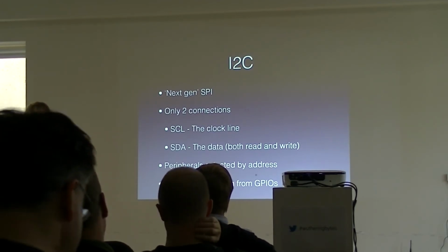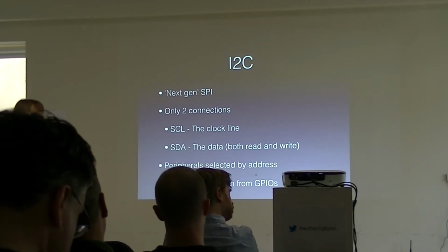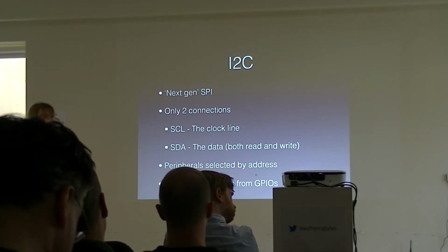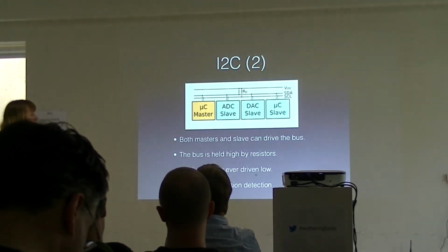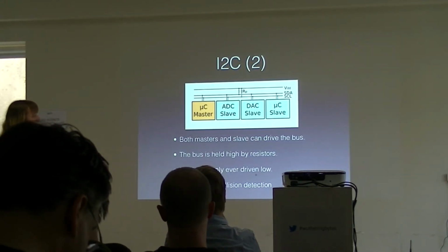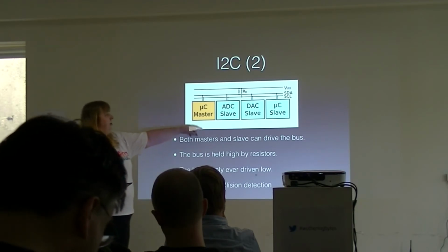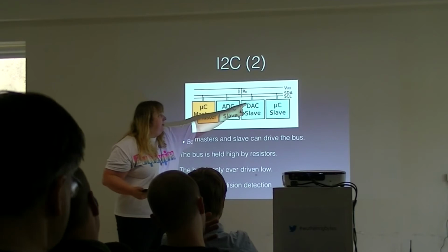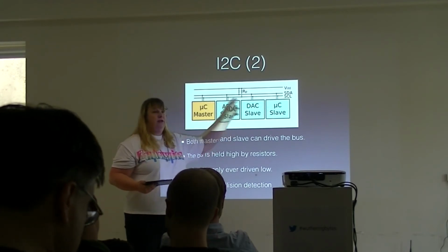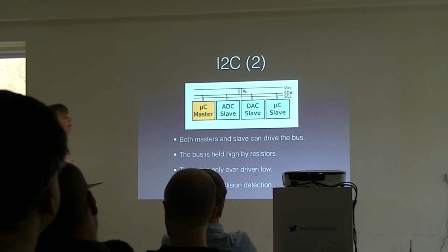Most microcontrollers have an I2C bus built in. So with I2C, you've got your microcontroller and then you just connect the SDA and the SCL from each of the chips you want to drive together.